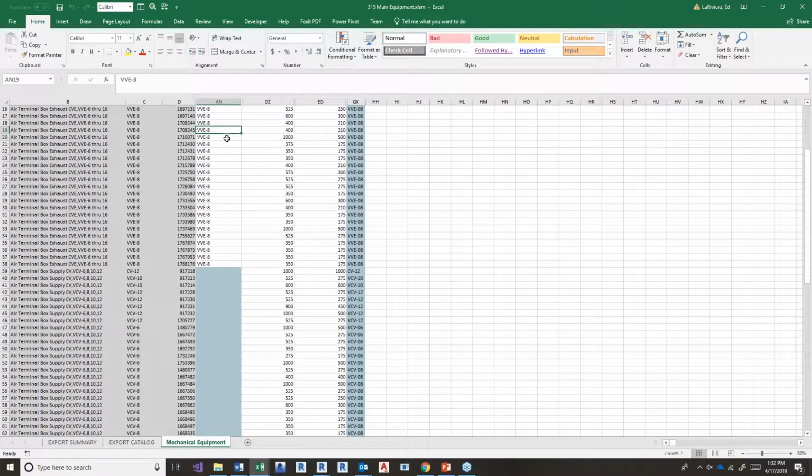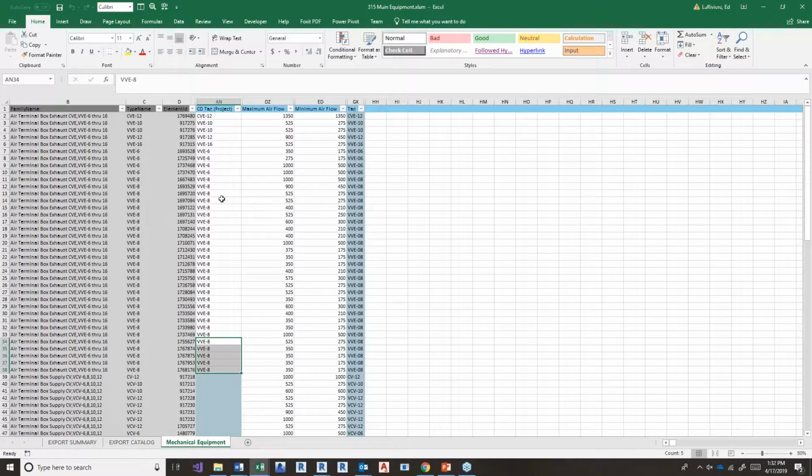We've got a library of families in which some of the parameters are set to instance values and other ones are set to type. So this would be an example of how we might use this model, or we might use BIMrx as a QA/QC tool. Like, we would want all of our CD tags to be correct unique identifiers. But these are not the unique IDs.